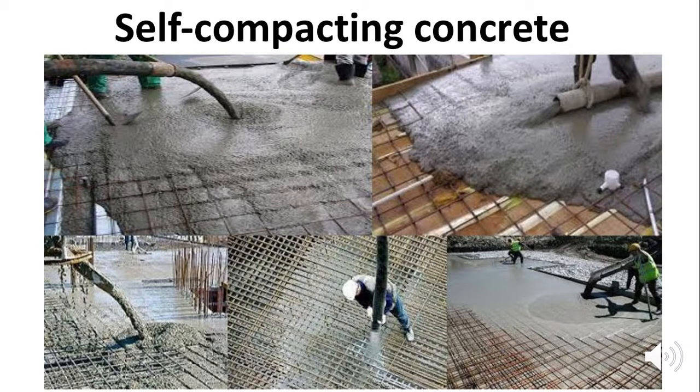Then we have self-compacting concrete. This is also another special type of concrete. Those of you who have watched one of my first videos here, it's on self-compacting concrete that I've developed a lot of interest with, and it was one of my projects that I worked on, trying to incorporate a self-healing effect in self-compacting concrete. I think this is one of the exciting types of concrete. It is self-leveling. You pour it and it will fill into any gaps, even in the congested reinforcements.